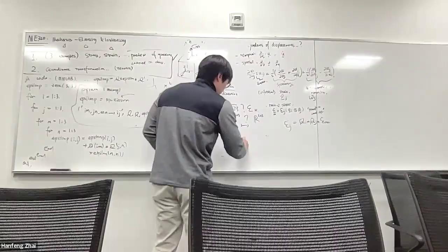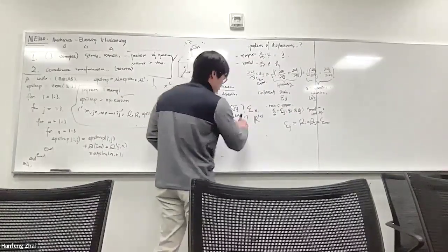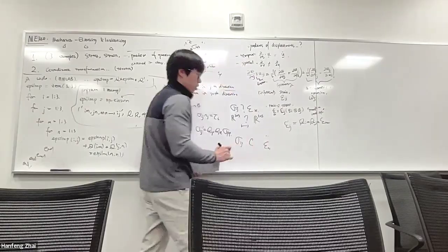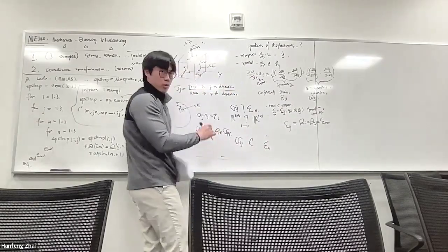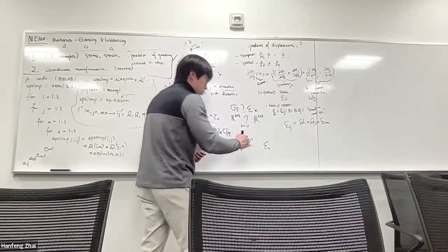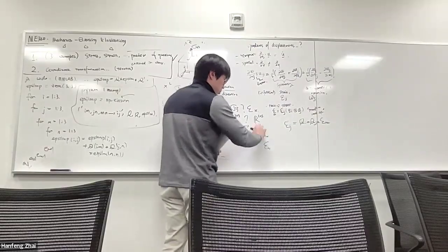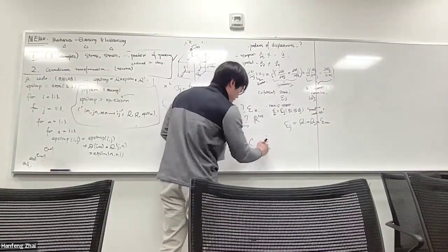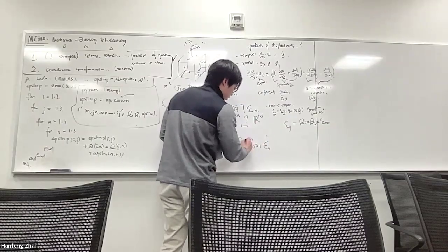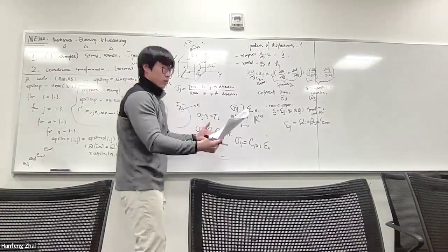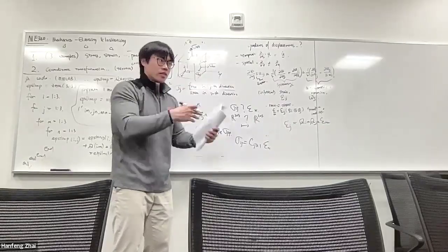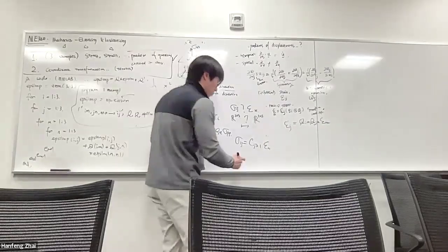So basically here we have stress sigma ij and strain epsilon kl. This is a second order tensor, or rank 2 tensor. We need a rank 4 tensor to represent the transformation from index kl to ij. It's C ijkl. And what will be the dimension of the fourth order tensor, or how many degrees of freedom do we have?